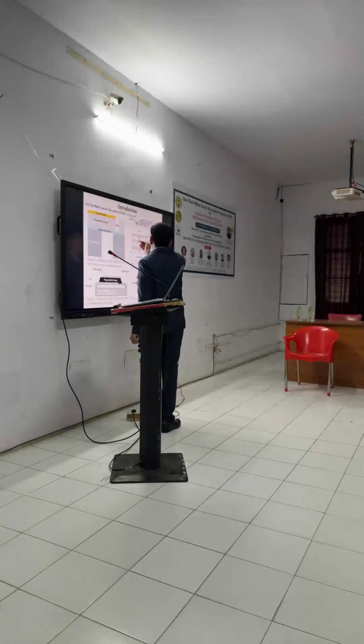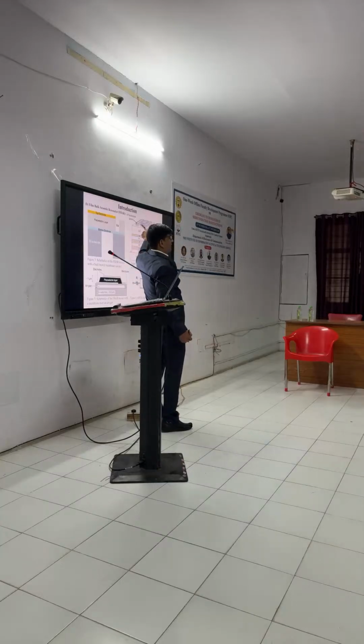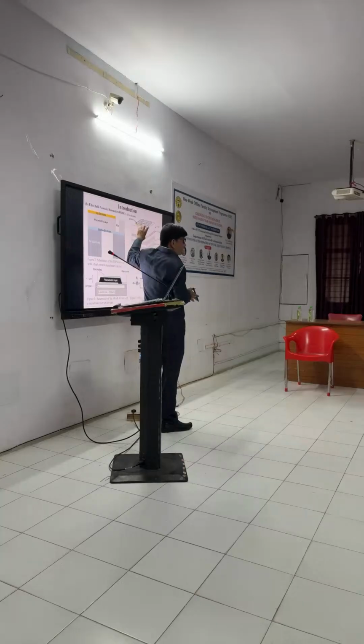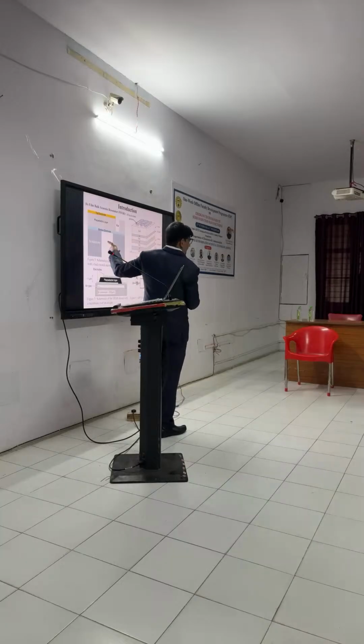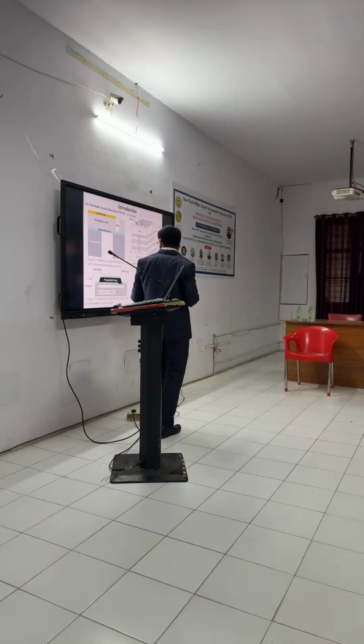So this reflector will work as a mirror for my acoustic signal. Once it comes to the bottom electrode and then to the mirror, it will reflect back to my ZnO layer, so it will travel back and forth within my ZnO layer. Clear? So here also we can confine our acoustic signal with the help of a mirror, as compared to a cavity. But on the top side we again have air. Okay.